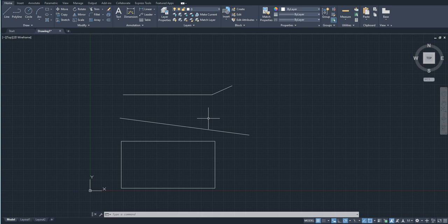Basically that is because you can avoid any confusion while making an AutoCAD drawing. Don't worry, the workspace of the AutoCAD is large enough. It can accommodate projects as big as the earth. So of course that's going to be heavy, but let me just tell you that you should just make your drawings in the scale of 1:1.